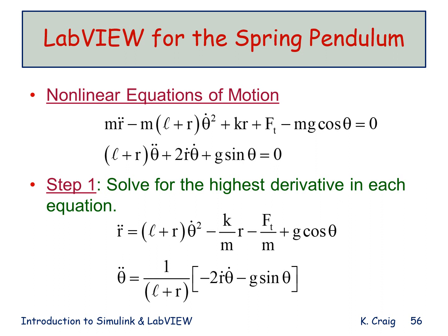The steps that precede the programming in LabVIEW are the same as the steps that precede the programming in Simulink. Step 1, we solve for the highest derivative in each equation. You can see that in the first equation, we have solved for the second derivative of r with respect to time. In the second equation, we have solved for the second derivative of theta with respect to time.